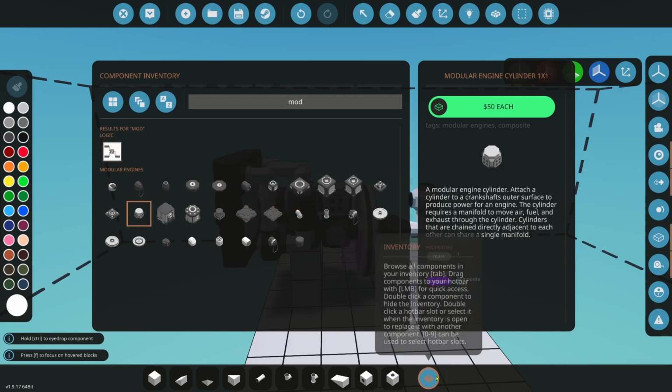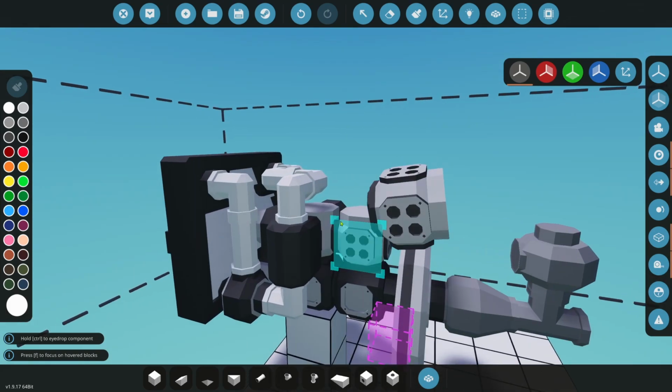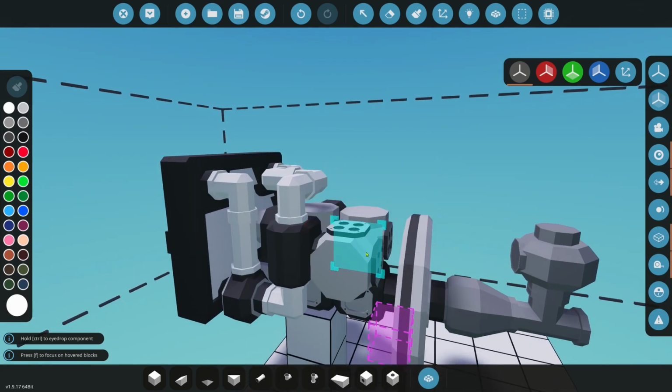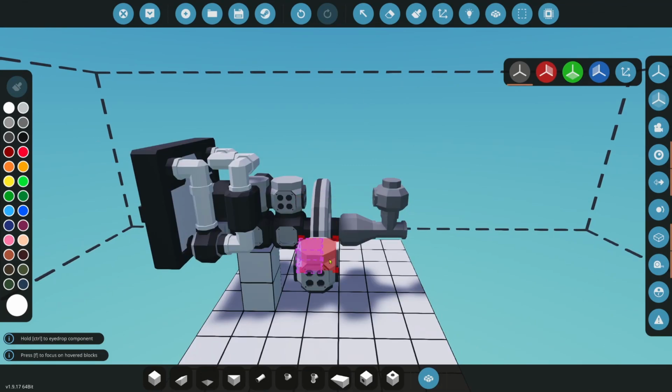So we have a weight of 4. It doesn't really work like this, but it would work like this IRL, as the parts are moving, so that's like a mass of 4 moving. It's not that much mass. Well, now if we add the flywheel, it's 104 mass moving. And so therefore, our engine is not going to want to change RPS very quickly.